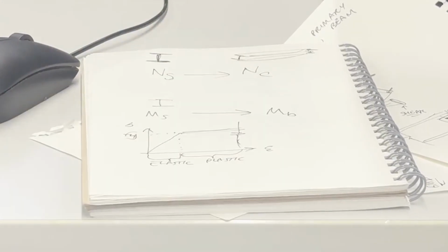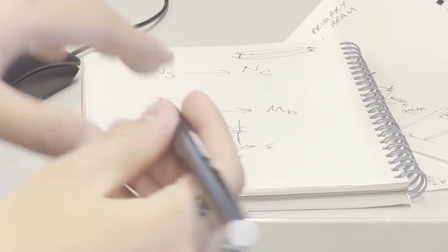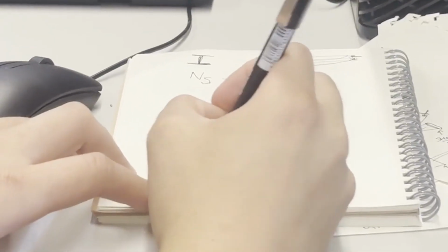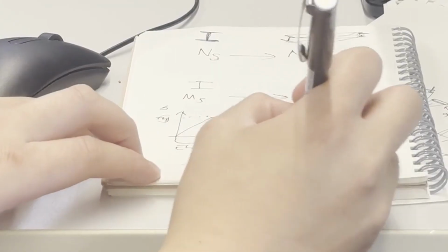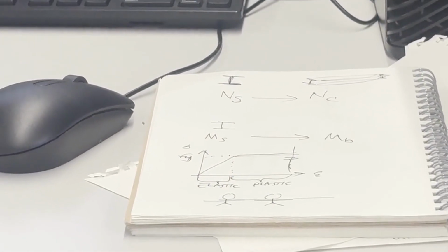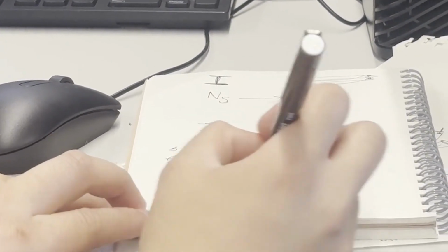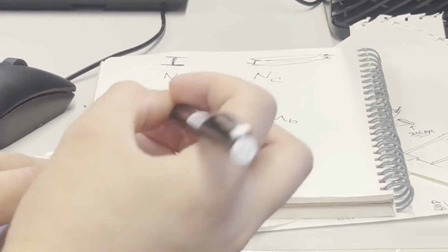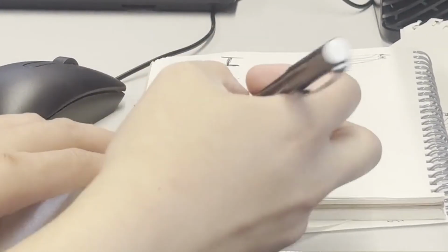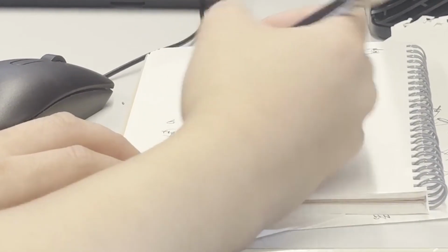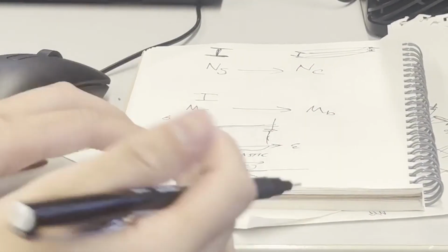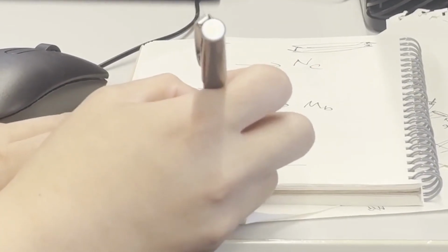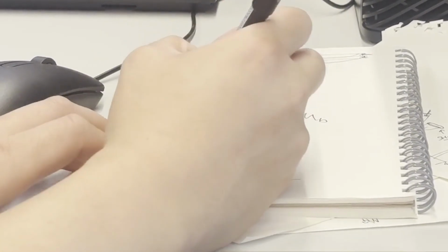At the point where it yields, it reaches a flat plateau in the material curve, and that's called the plastic plateau, right? The best way I can explain this, I came up with this analogy this morning for solid mechanics because they're learning about something very similar. Imagine you're playing tug of war, 1v1, right? And basically this person's starting to win. They need to put in more and more force. So this person's pulling a bit more than this person, but that's all elastic.